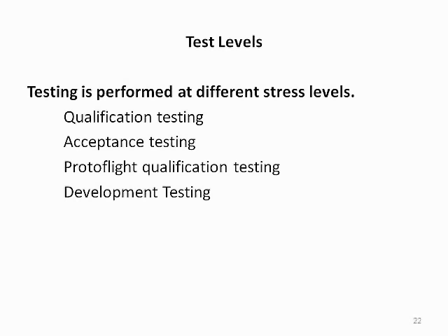We will now turn our attention to the different levels of testing performed on spaceflight hardware. Testing is performed at different stress levels and for different purposes. The most common categories of test are qualification, acceptance, and Proto-Flight or Proto-Qualification, and development tests.